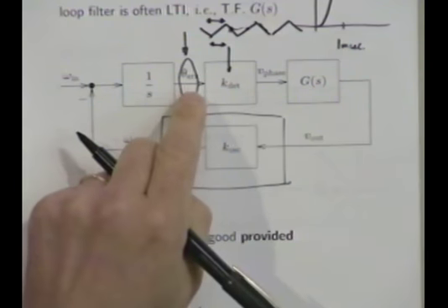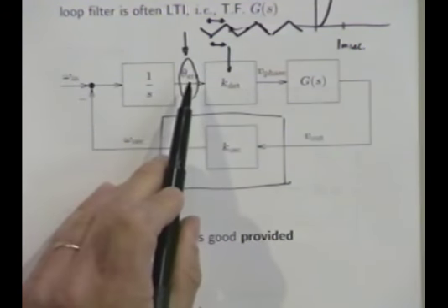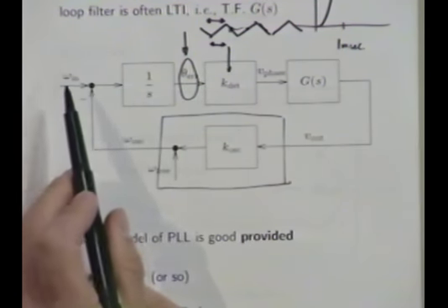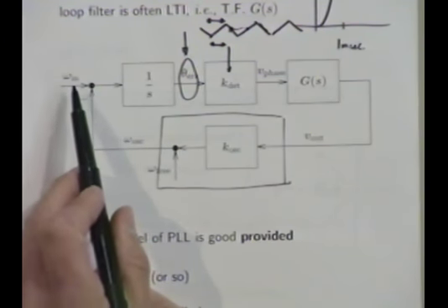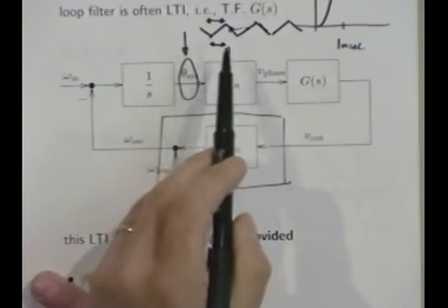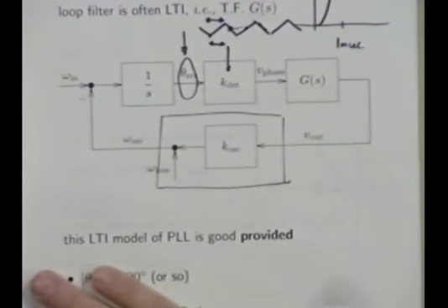And there's lots of interesting things to do. For example, we can work out the DC gain from omega in to theta error. Very interesting number. Okay? Because that'll tell you the lock range if omega in were very slowly varying, right? If I vary this thing too much, this thing gets out of its 90-degree band, and this model is completely wrong, and the whole thing goes nuts.